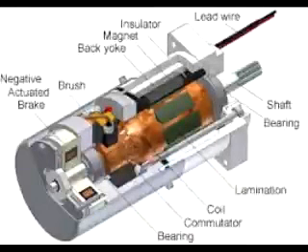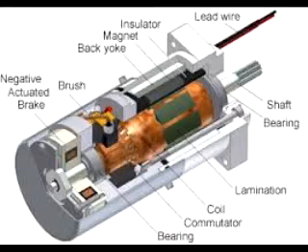The torque from a permanent magnet brush DC motor is limited by its stator field, which gives it good low-end torque and a limited high-end torque. The permanent magnet brush DC motor responds very quickly to change in voltage. This is due to its constant stator field, thus giving it good speed control capabilities. But they do have a drawback. Permanent magnet brush DC motors will lose their magnetic properties over time, thus degrading its stator field and causing the motor performance to decline.